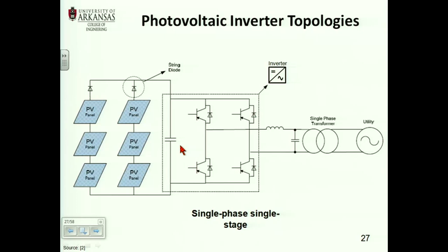The energy comes also from the capacitor. Remember, the capacitor can change the current quickly. And so any transient on the AC side can be provided by this capacitor. So the capacitor there is for improved dynamic response.